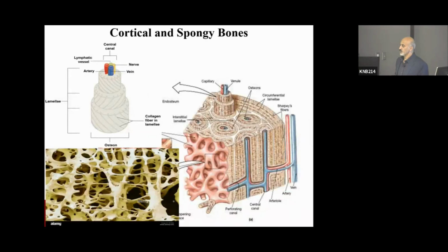The slope has changed. Then if I remove the load, at the end of the day, I see that loading is this one, but unloading is this one. And at this point, the stress is 0, but the strain is not 0. What does this mean? This means that if I apply load on my bone and I exceed the yield point, of course, there would be permanent deformation and dissipation of energy, micro cracks production.